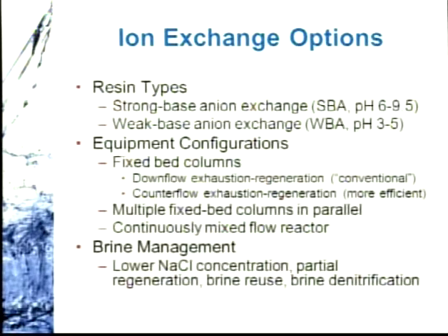So ion exchange, as we described very briefly yesterday, is a resin-based treatment technology. So these are very small, 1-ish millimeter sized resin beads, polystyrene type beads, that have functional groups that will remove anions.